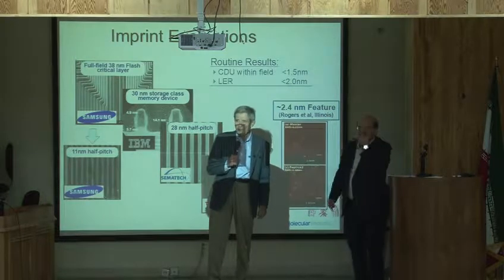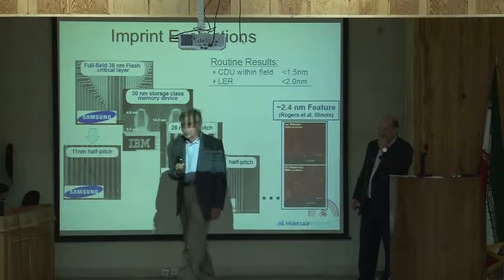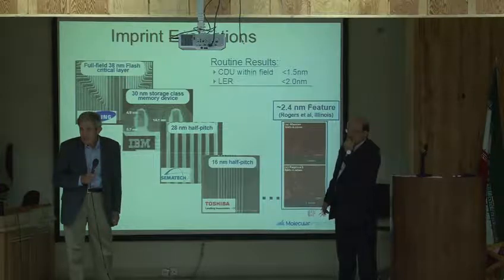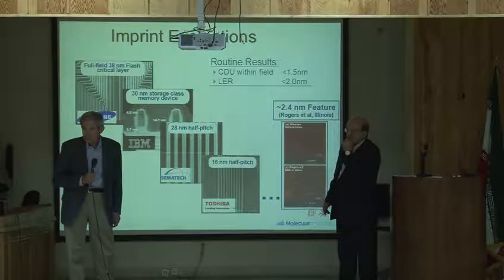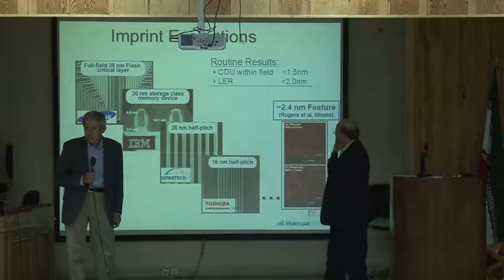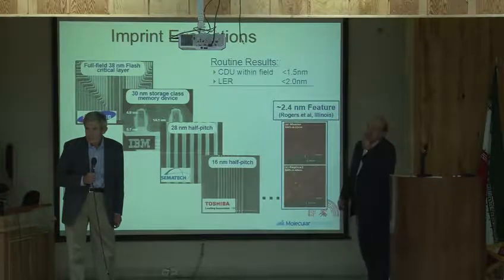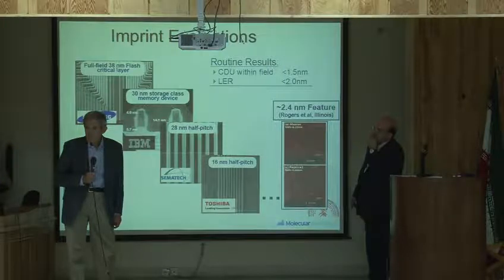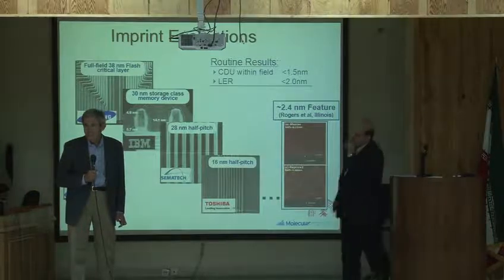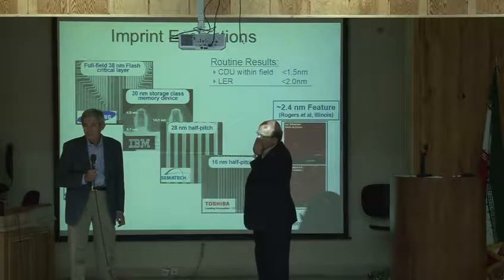That's excellent. Actually, I have a question about the dimension of the TSVs. You told that in a monolithic integration, you are using two silicon layers, okay? So how large are your TSVs? Because it can literally impact the design partitioning approach. If we can implement small TSVs, we are free to design our whole system in multiple layers and we are not limited by the number of TSVs. But when we have large TSVs, the number of TSVs is limited and the granularity of the design partitioning should be large. I mean, the diameter, for example, how many micrometers or nanometers?